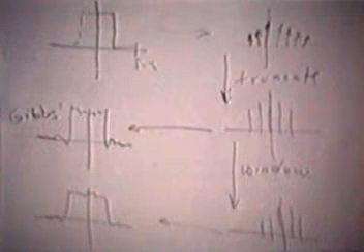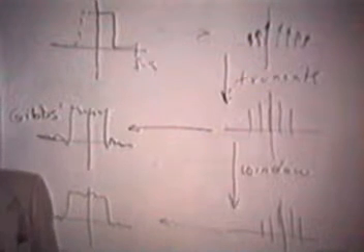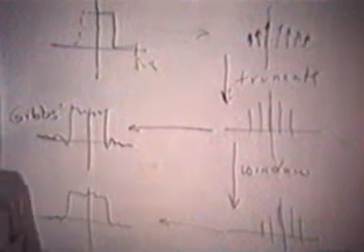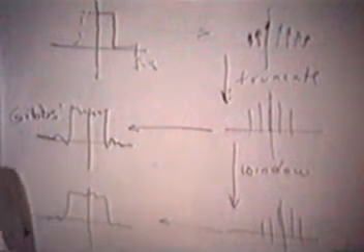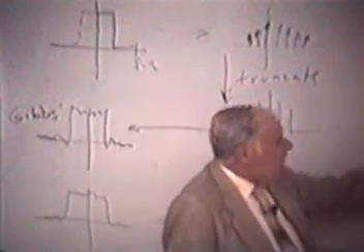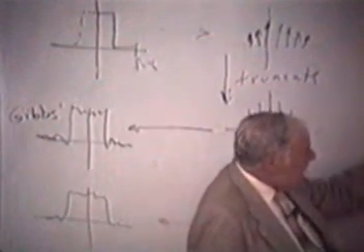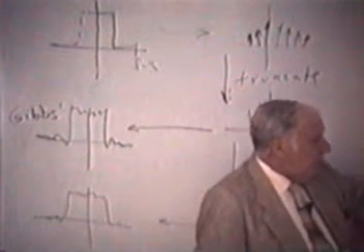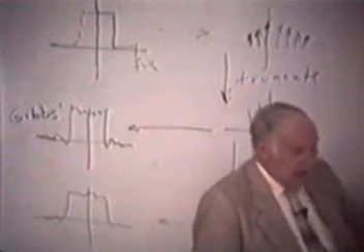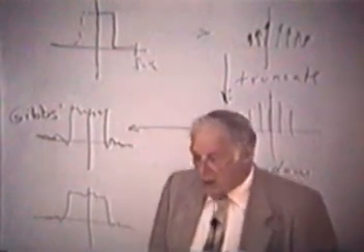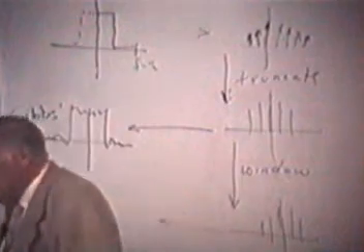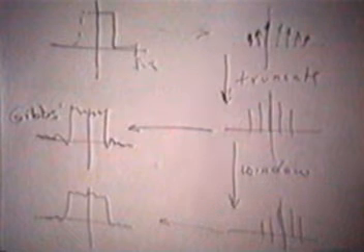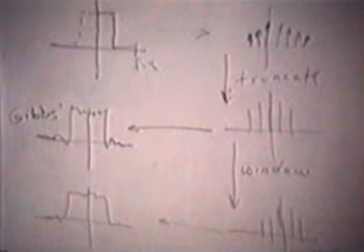Well, Kaiser did something more than this. He tried to answer those questions. And so what he did, and I'm recommending to you the method he used, he designed a bandpass filter with bounds of size delta and transition zones delta F. And he wanted the signal to stay inside that bound. So he gave two numbers, A and delta. You calculate minus 20 log of delta, then you calculate n, the number of terms, which is this.